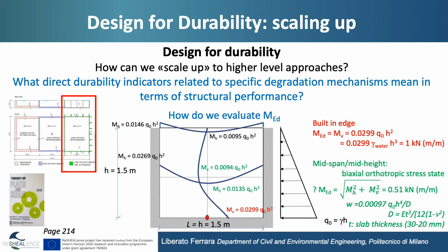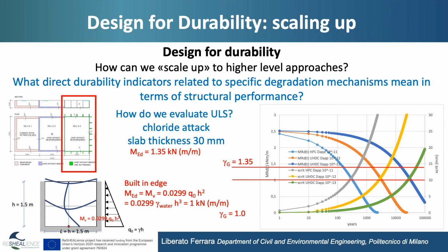Well, according to the same procedure that we have seen before, if we use 1.35, we have the moment degradation curves, which you can see here, once again in light blue, orange, and dark blue for the chloride degradation mechanism. And you can see that we arrive at maximum capacity for a very long time, sometimes after 100 years or even more. Is this really representative of the behavior?